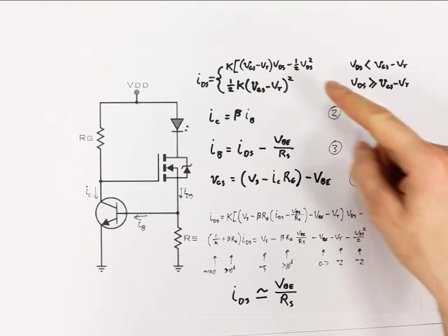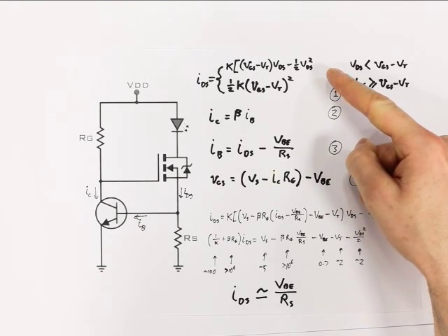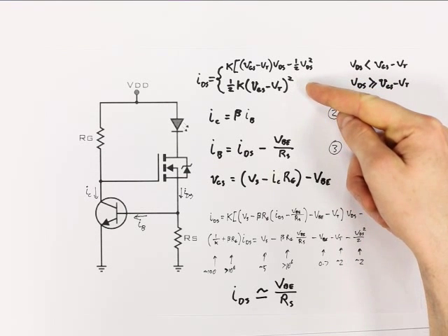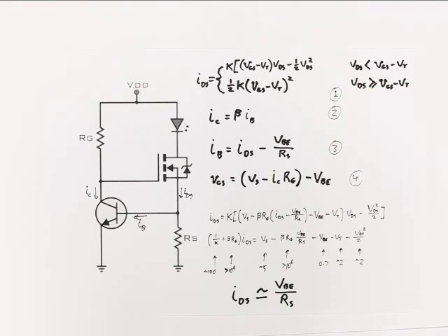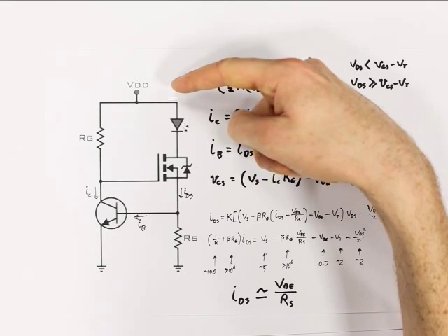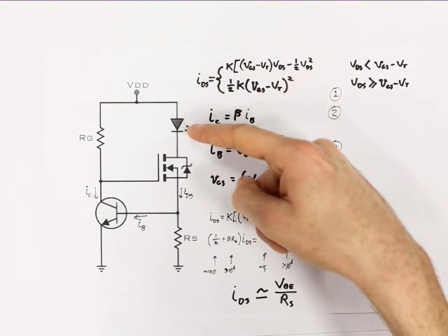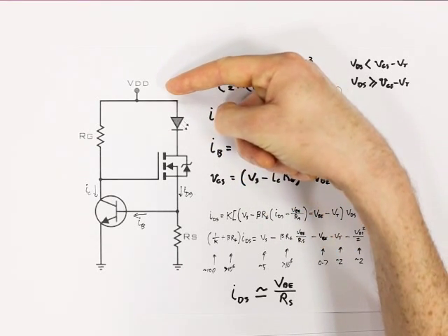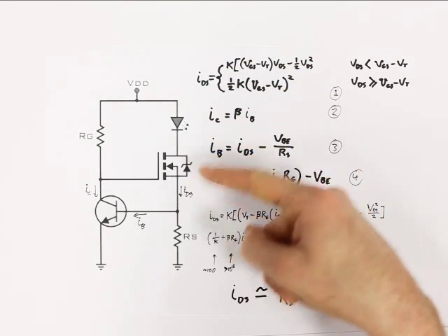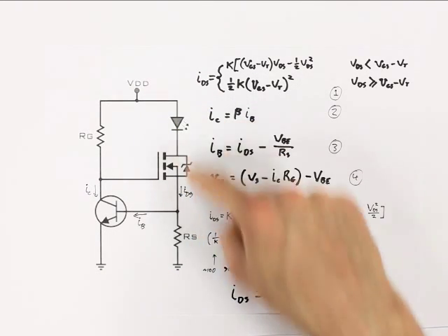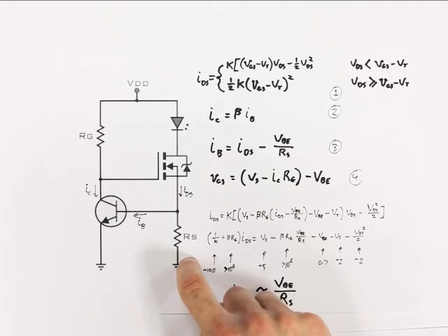And that was for the MOSFET operating in the triode region. We could repeat all of this using the saturation region equation instead, but we just get a similar result. What determines whether the MOSFET operates in triode or saturation is actually just how big the supply voltage is compared with the LED forward voltage. Because if you've got a very high supply voltage, then the MOSFET is going to have a greater drain source voltage in order to get rid of that before it hits ground, effectively.